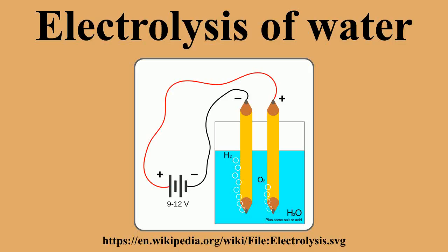and can reduce the overall cost of hydrogen produced. However, observing the entropy component, voltages over 1.48 volts are required for the reaction to proceed at practical current densities. In the case of water electrolysis, Gibbs free energy represents the minimum work necessary for the reaction to proceed, and the reaction enthalpy is the amount of energy that has to be provided so the reaction products are at the same temperature as the reactant. Potentially, an electrolyzer operating at 1.48 volts would be 100% efficient.